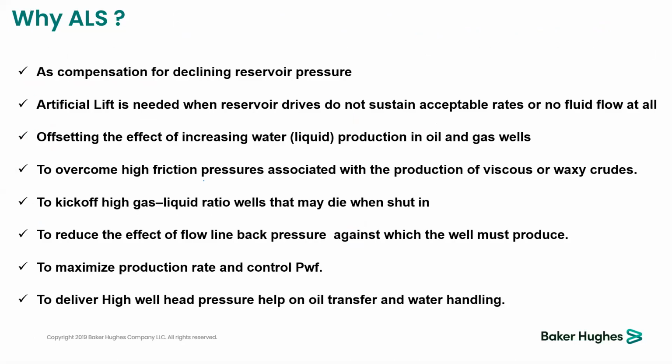Why should we have an artificial lift? Initially, for any new oil wells, the reservoir pressure is at a high value. So the reservoir pressure is enough to deliver the fluid to the surface. But after some time, there is a decline in reservoir pressure. So we have to get the tools to compensate for the decline of reservoir pressure. That's the first reason why we need to have an artificial lift.